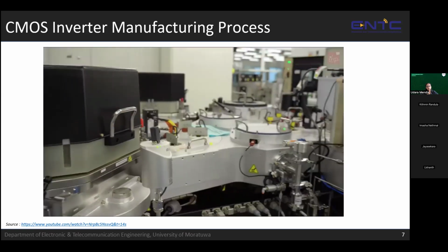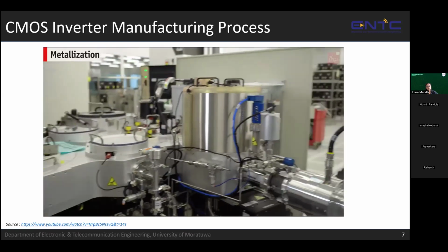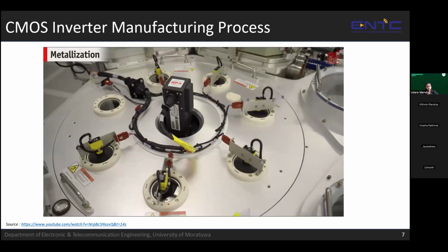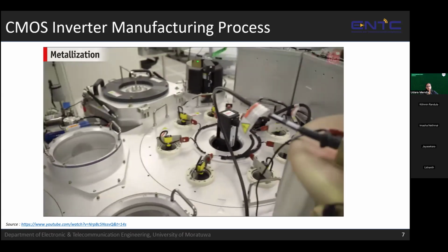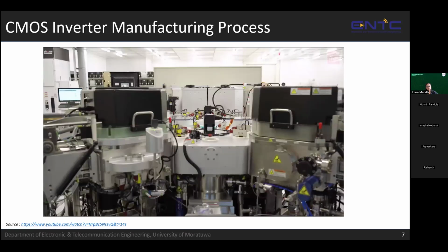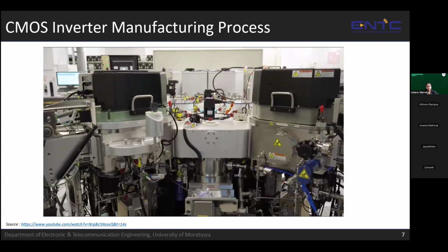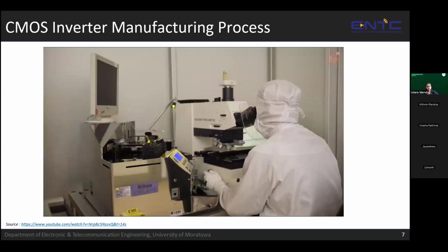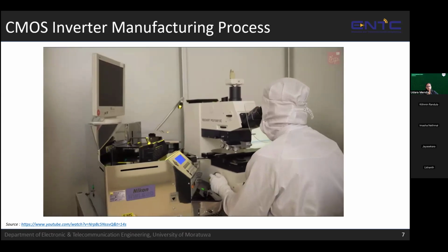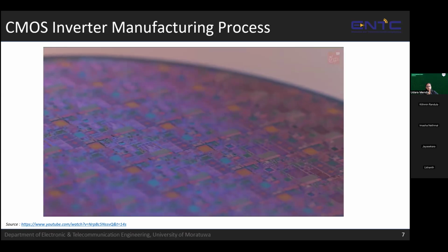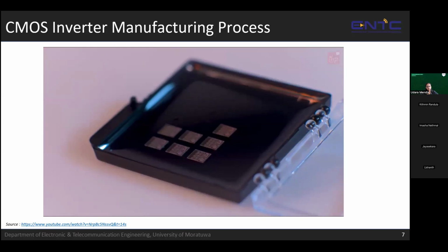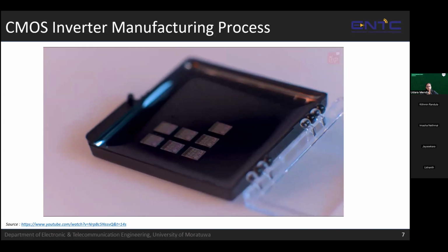To electrically interconnect our active devices, we use metals such as aluminum and tungsten. For example, a sputtering process allows us to deposit aluminum. This means that an aluminum target is bombarded with charged particles that knock off aluminum atoms. The sputtered material lands on our wafer and forms a conductive film. Using photolithography and reactive ion etching, the film is patterned and the interconnects are created.